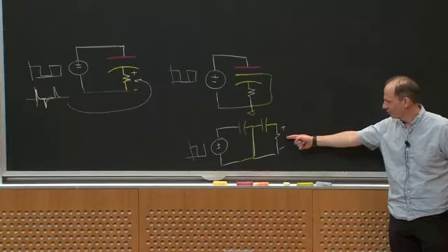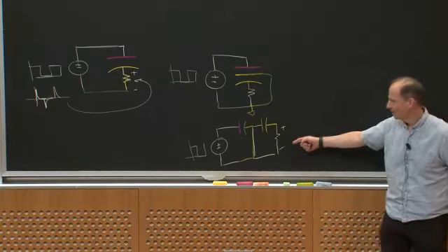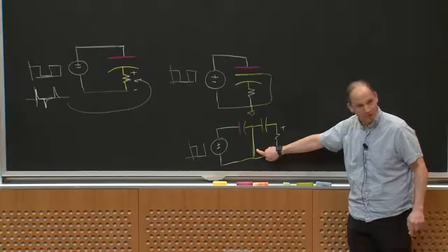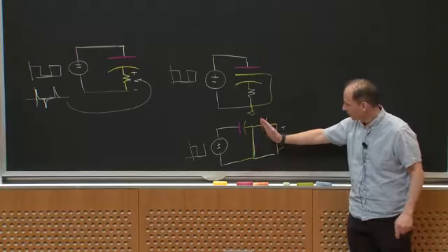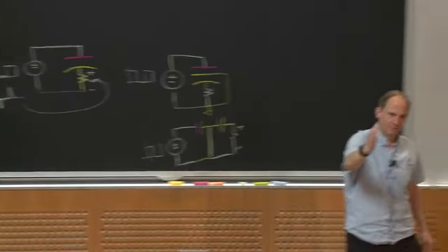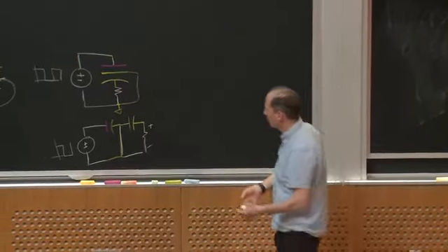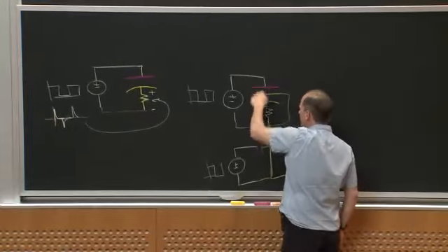Am I going to see a voltage over here in this circuit? No, right? I mean, he's got a grounded capacitor over here. So essentially, this piece of metal acts as an electrostatic shield, right? If it was all the way around, you'd call it a Faraday cage. But it prevents this noisy signal from injecting onto this.